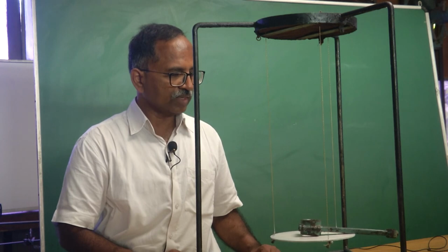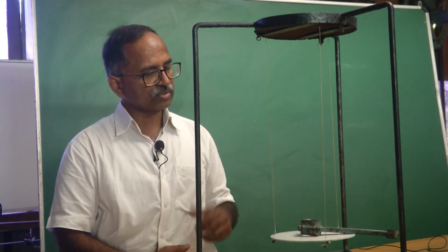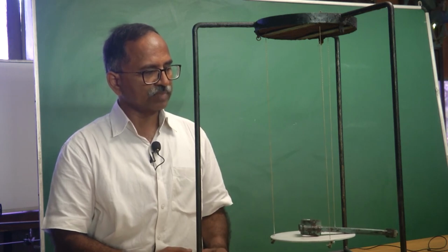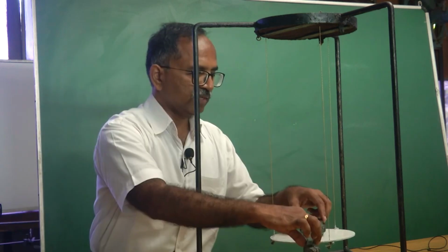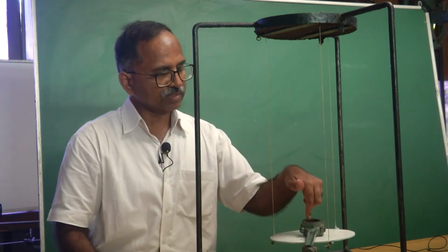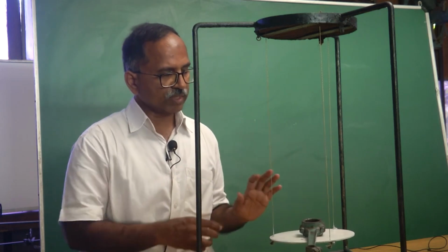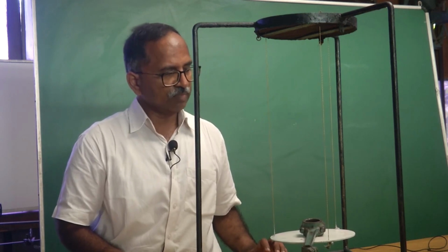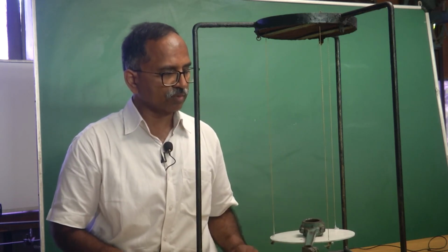And you can notice that the plate is generating an oscillatory motion, and this free vibration response can be recorded and we can find out the period of oscillation. Place the connecting rod with the axis of the plate aligned with that of the big end of the connecting rod, so that whatever value of mass moment of inertia I get will be about the axis of the big end of the connecting rod.